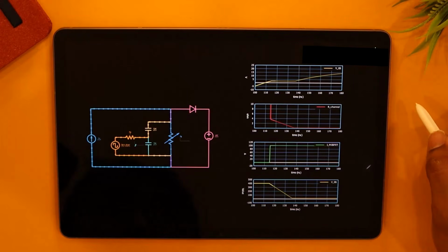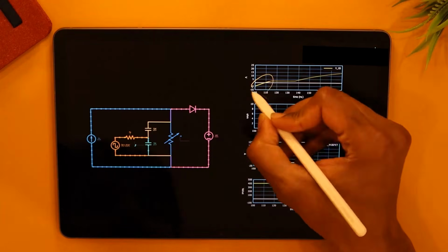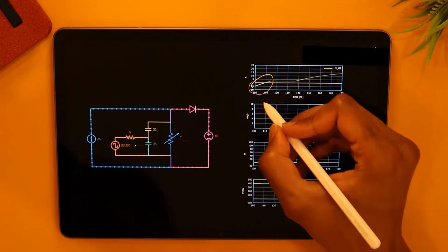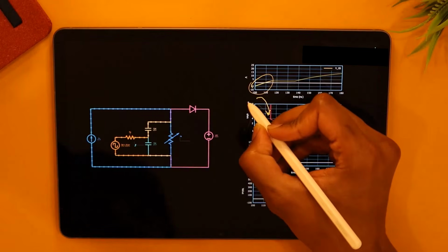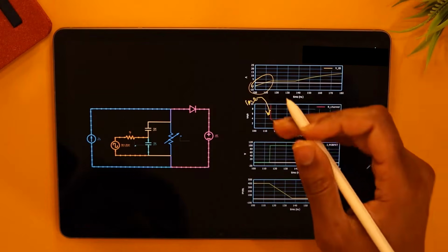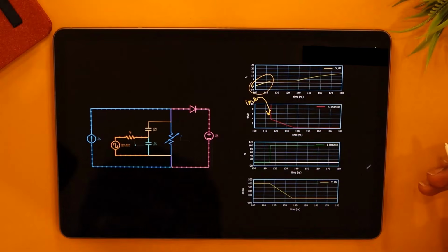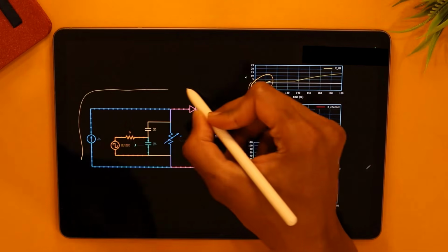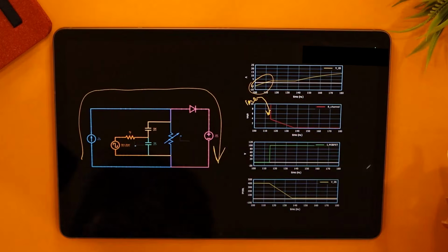Before the plateau region, which is what is highlighted here, the gate voltage is continuously rising. The channel resistance is falling from that 1 mega ohm really high value, aiming to go towards 0 ohms. It's not quite there yet. Now, before the plateau, the MOSFET is off, the entire current is carried by the diode.